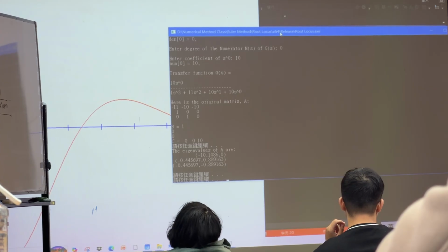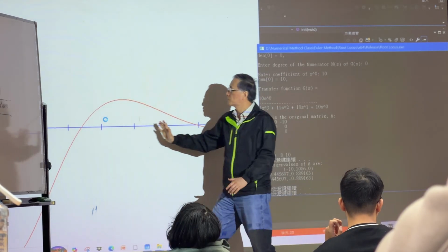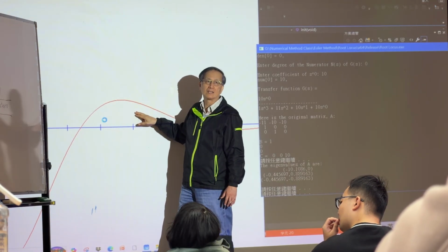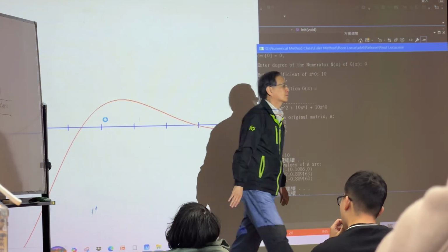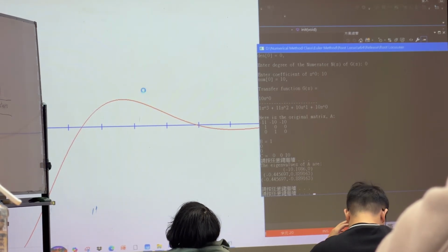You see, it jumps up because this is like a second order system, right? So when the k value gets higher, the response time is shorter, faster, but the overshoot also gets bigger. Likewise, let's do it again. Let's go to 20 and see how we go.